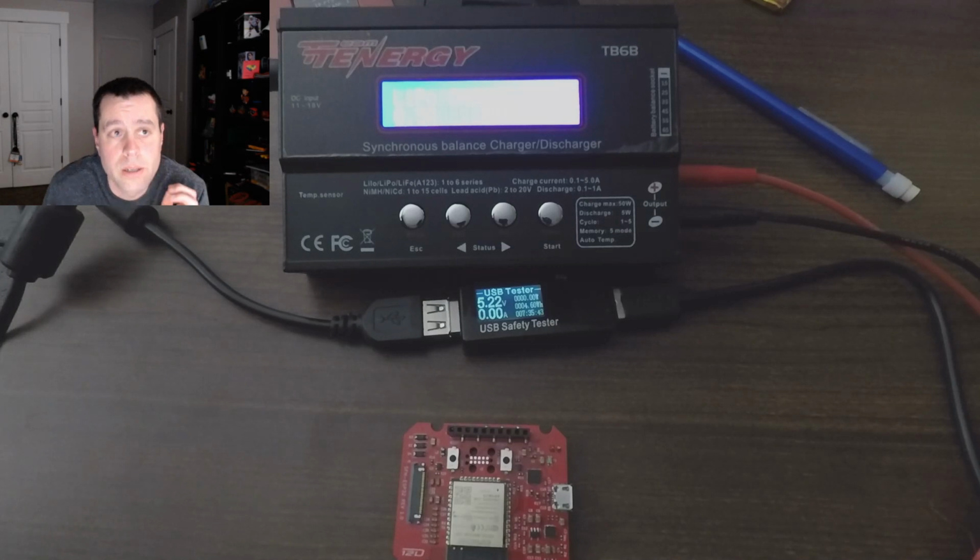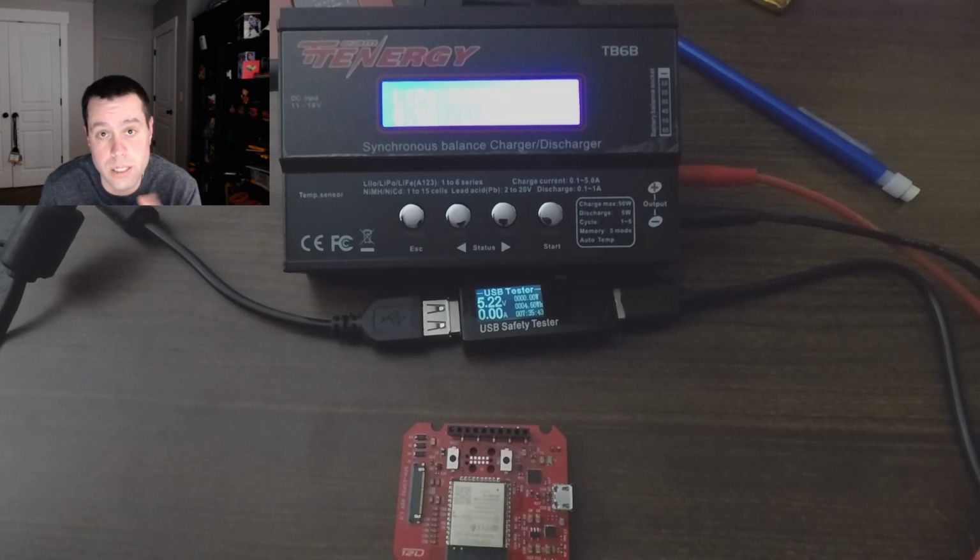This is an example of where if it doesn't cost anything, and in this case, I'm talking two resistors, I just have to do a voltage divider, and that's going to be cents. And if I can get the current, which I believe there's no reason that I can't just use higher resistor values, and then the quiescent current on that will be negligible.